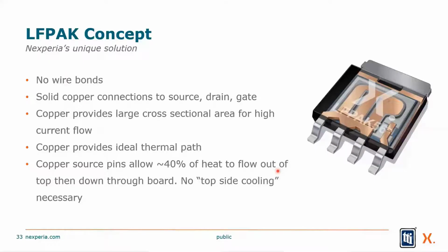Remember what LFPAK is. It is different than pretty much every other MOSFET in the marketplace because it uses what we call copper clip technology. You can see in this cutaway diagram, this is of the LFPAK56. On the bottom, I have this gold plate. That is the drain connection. That is the big heat pad on the back of the package. I solder that right down onto my circuit board. So it's the primary way that I get heat away from the junction, away from the piece of silicon, down into my system for cooling.